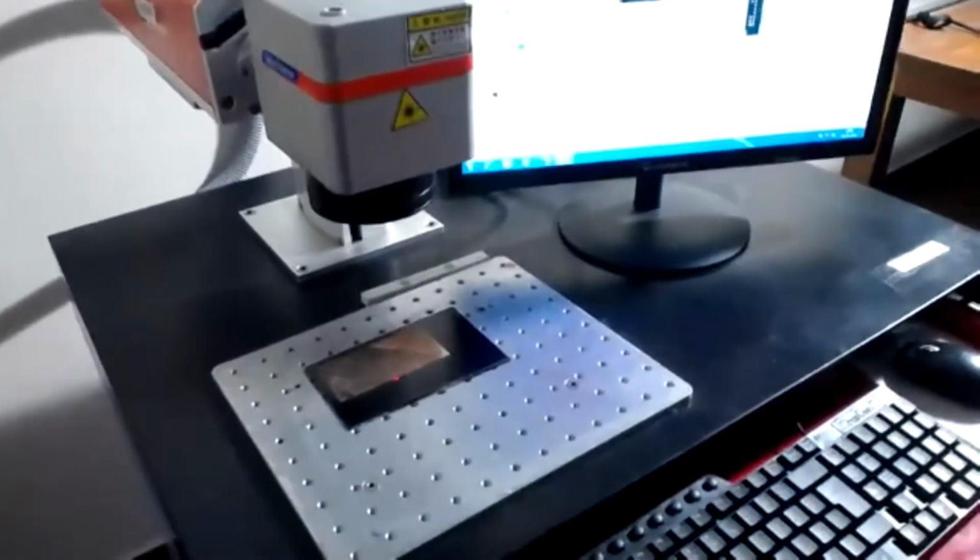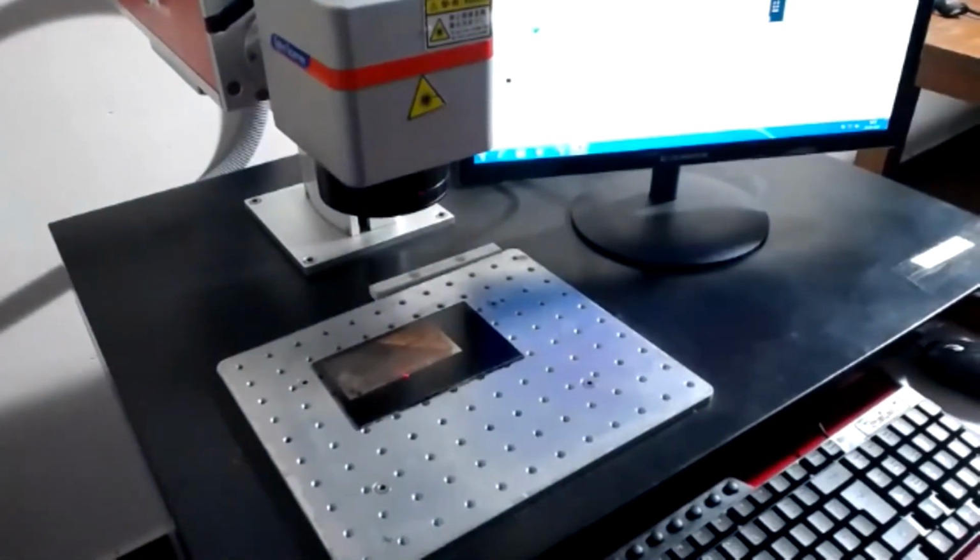These parts we cannot be doing here. We have to concentrate when you do the circuit part. So when you concentrate on the circuit part, you should be very clear that the design rules are followed. Otherwise, what really happens is you will get interference of signal, especially if you go for low frequency devices. If you want to design something like an Arduino board, you will not get much problem. These are low power devices, there is no problem. When you go for buck converters, or a very high frequency signal like RF signal devices, RF design, then such things we should concentrate on. The design methodology, multi-layer, those need to be kept in mind when you go for high frequency or RF design.